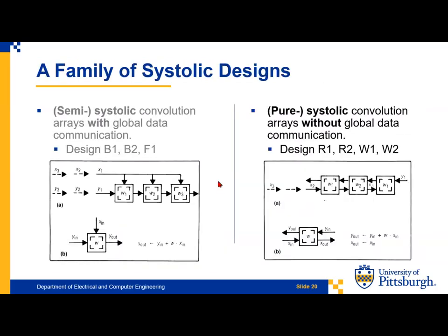Okay, so in the previous slide, we introduced the semi-systolic convolutional array. The semi-systolic convolutional arrays with global data have a global buffer and broadcast the input data to each processing element. And next, we will introduce the pure systolic convolution array without global data communication.